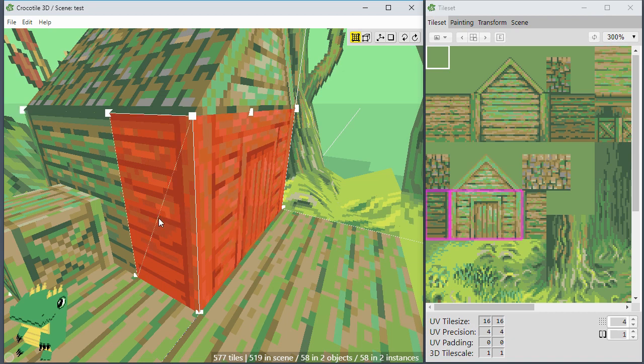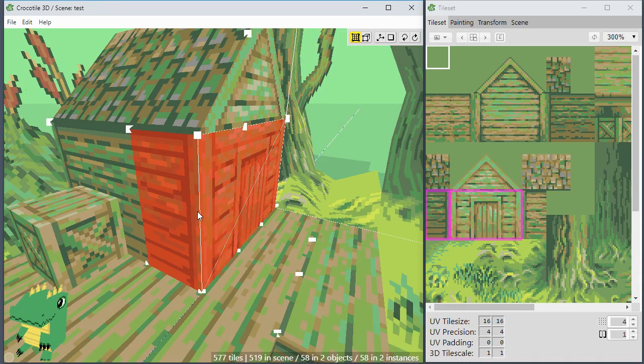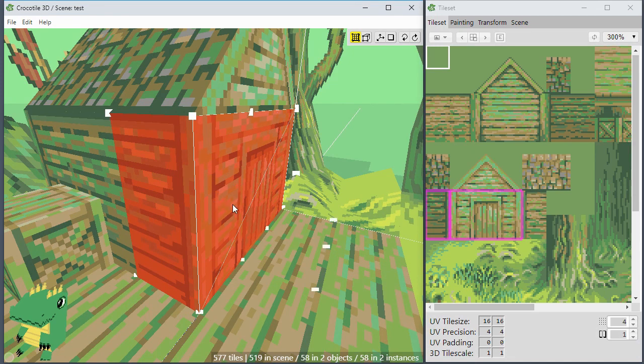You would see the shadow blended between these two tiles if you have it smoothed, with the vertex normals averaged together. If it's just flat, then you'd have a very hard shadow, a hard edge to these polygons. I'll illustrate it once we export some objects and import them into other programs. We'll be able to see the difference between a flat vertex normal and the smooth one.